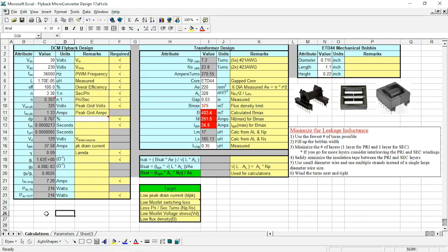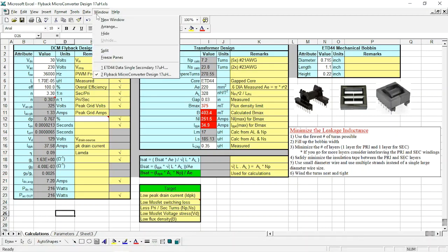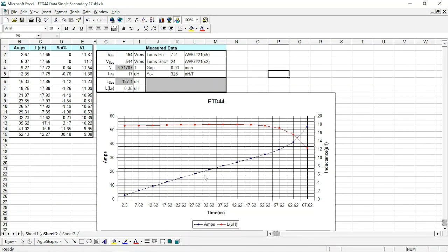Paul, why is it only a 100-watt inverter if you can get 216? Well, the reason is, if you look at two things. The first thing you look at is the ID peak is 37.5 amps. If you looked at my earlier Instructable on the inductor saturation meter, I use that to show me what this transformer was going to do, what the performance of it is. So I wound the transformer and then I tested it, and I know that this is what I'm getting.